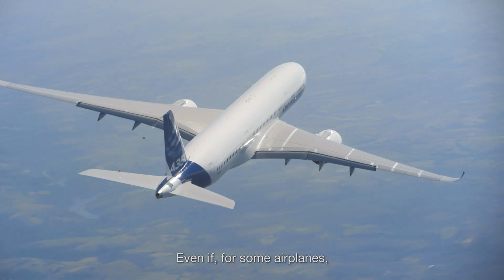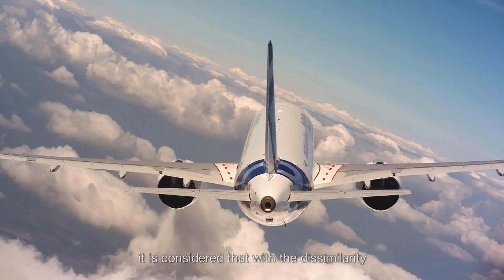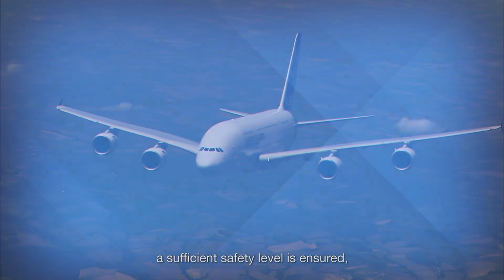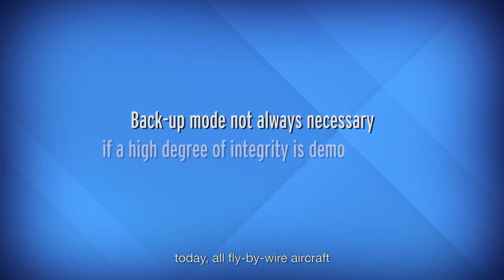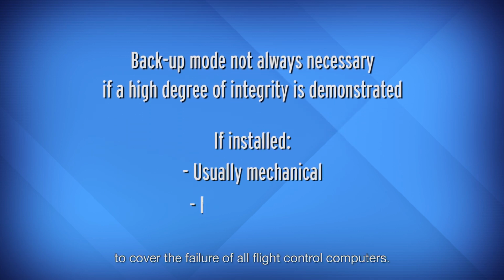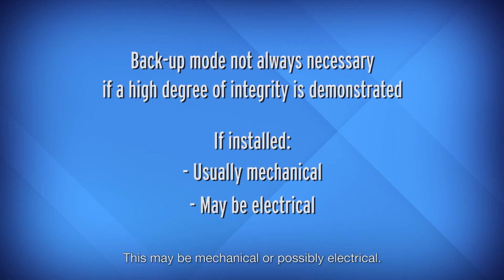Even if for some airplanes it is considered that with the dissimilarity and the general architecture a sufficient safety level is ensured, today all fly-by-wire aircraft include a backup mode to cover the failure of all flight control computers. This may be mechanical or possibly electrical.